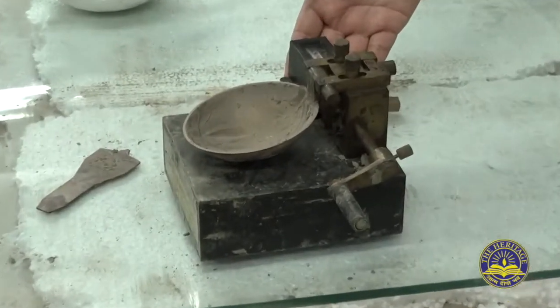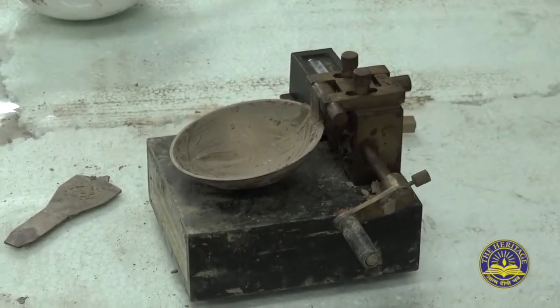So our next test is determination of Atterberg limits. Now there are three limits, which are liquid limit, plastic limit and shrinkage limit, and these are applicable for fine grained soil. So how to determine the liquid limit? You can see this is known as the Casagrande apparatus, and what you have to do, you take say 50